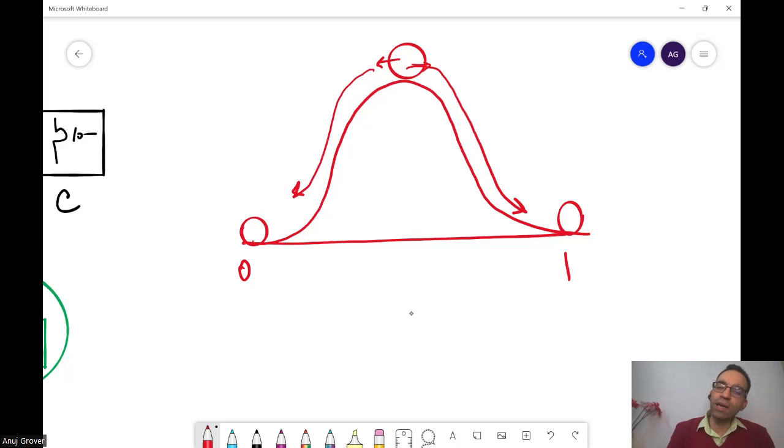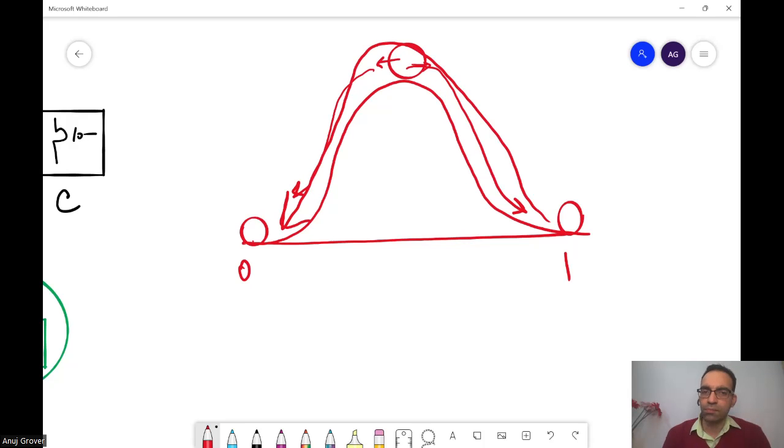Otherwise, if both my inputs are at VDD, if both the nodes of the latch are precharged to VDD, then one side will need to make an extra effort to go to 0. The other side is already 1. The first side will need to take an extra effort to go to 0. Are you able to see this?